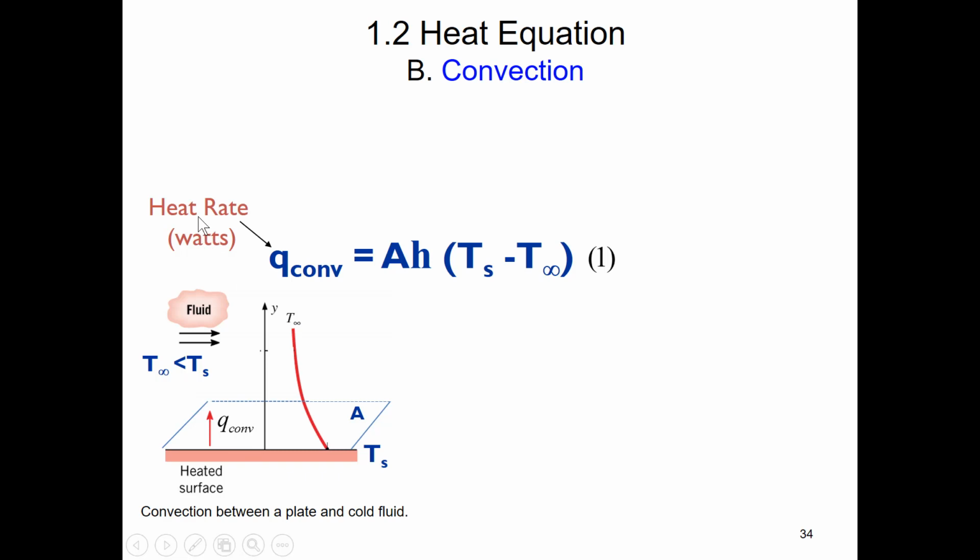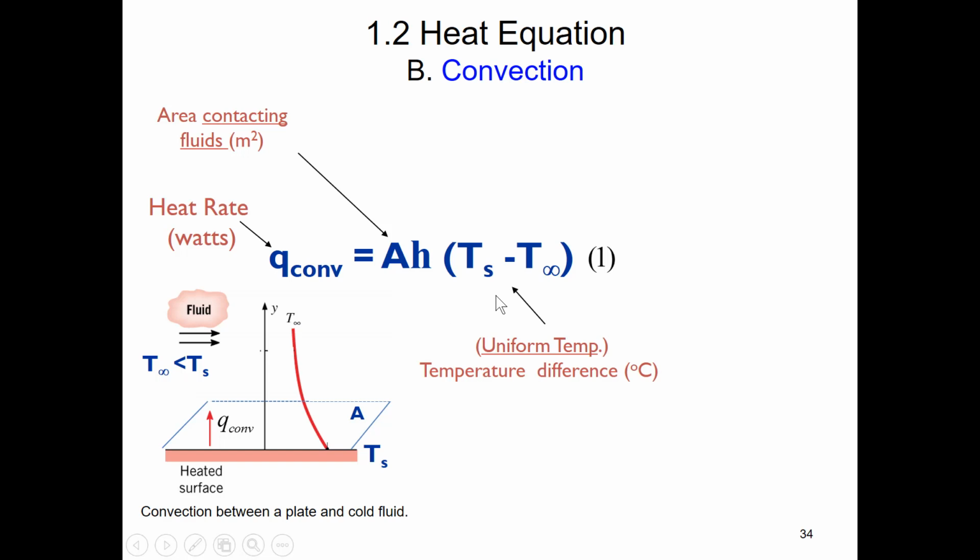And its heat rate can be calculated by area A, which contacts the fluid, times the temperature difference between solid surface and fluid, times heat transfer coefficient H in the unit watt per meter square per Celsius.